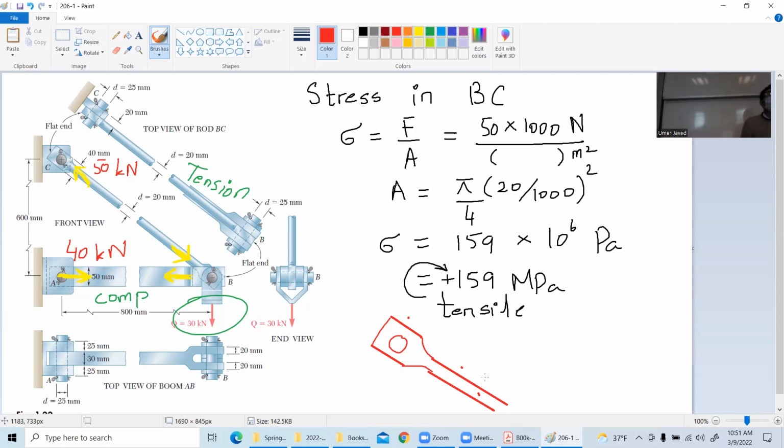So stress, right now I'm standing here, right? So thinking that right now I am standing here and this portion of the floor is not taking any load, that's just ridiculous. When I'm standing here, definitely this fellow is also feeling my load, right? The stress is being distributed. It's very concentrated where I am standing right now. So think of it like something that flows, I have a force that is going through it.